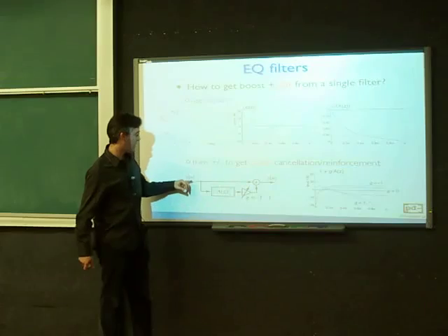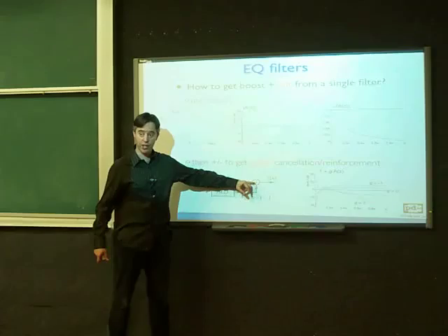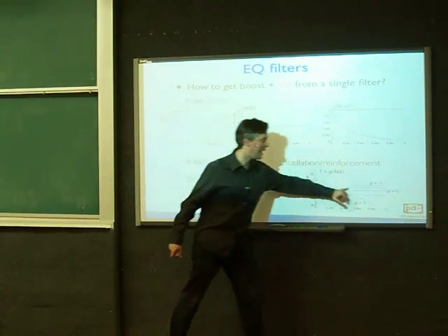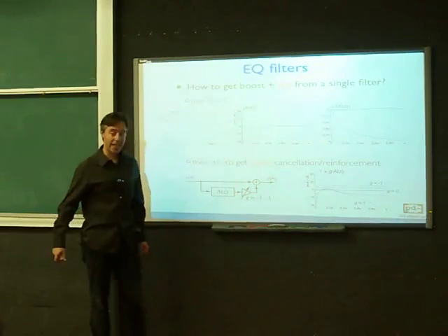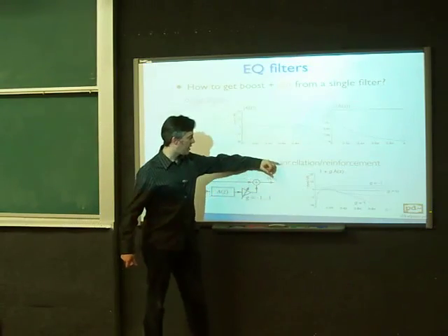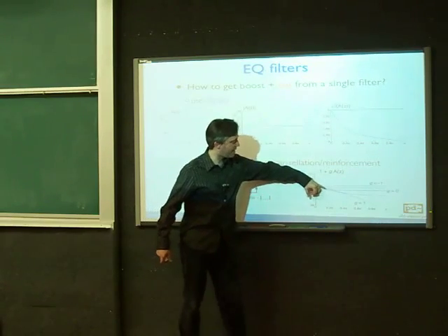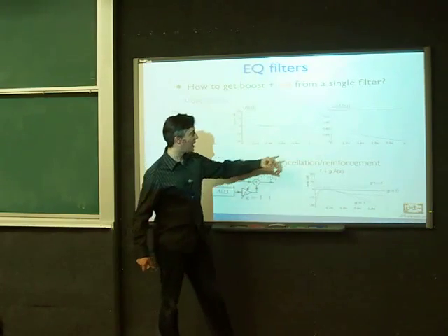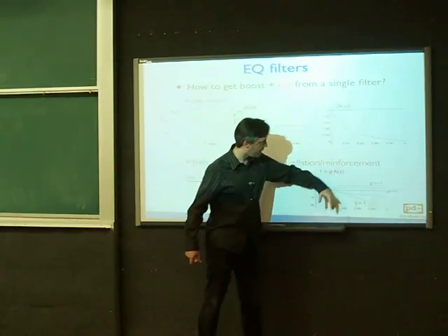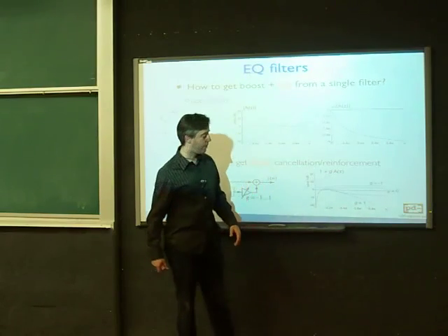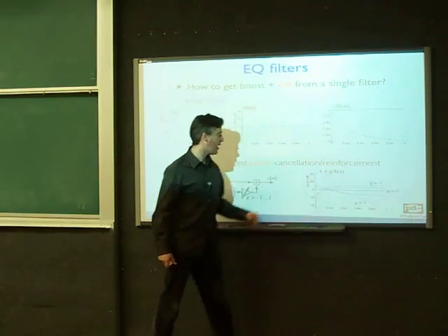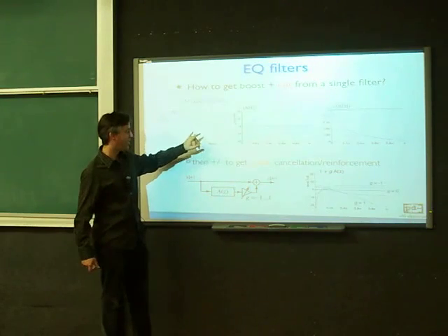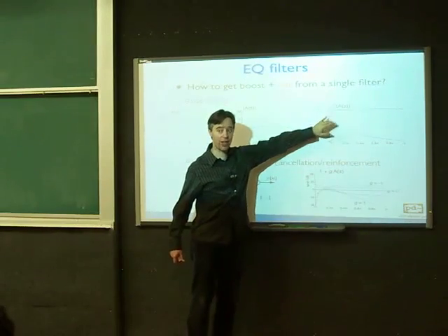And in fact, at the low frequencies, this is essentially just doubling the amplitude. Doubling the amplitude is raising the level by 6 dB. And of course, cancelling it out is lowering the level by infinity dB. So that's plus 1. So plus 1 down to 0 sort of just fades this low pass response more and more flat. 0 is flat. And then as we go negative, we're cancelling out the low frequencies now and at the same time boosting the high frequencies. And so we get this set of high pass filters. And then the crossover point here, the frequency at which they change, depends somewhat on how close these are. So this is what the shape of this phase response is.